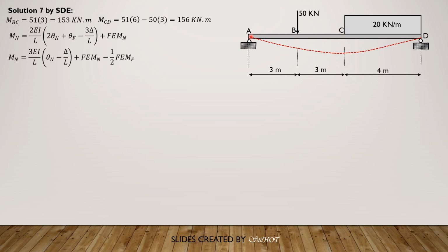So again, if the point lies on the left side of the beam or the section in consideration, the fixed moment is negative, and if it lies on the right side, the fixed moment considered is positive because it is clockwise. So it is counterclockwise here, then clockwise here. So negative at the left, positive at the right. So that's the sign convention.